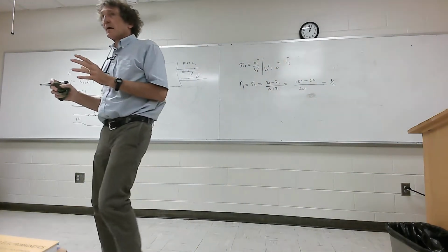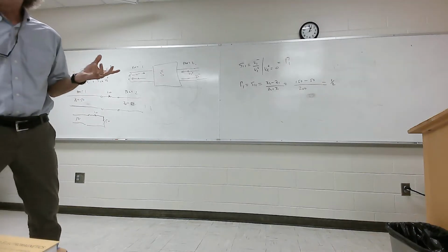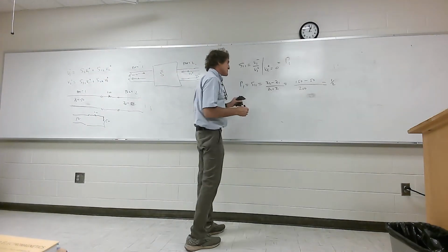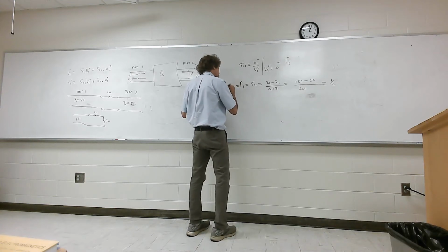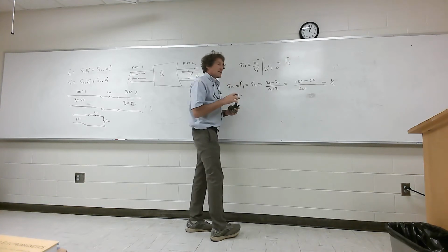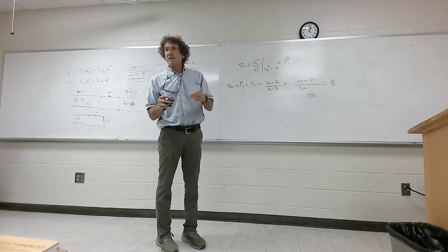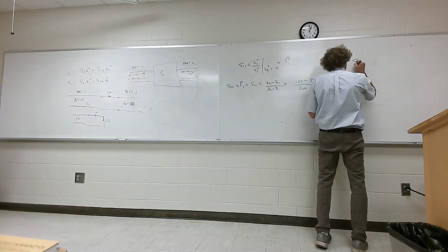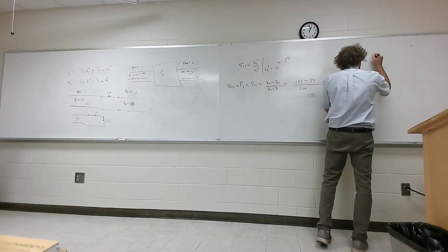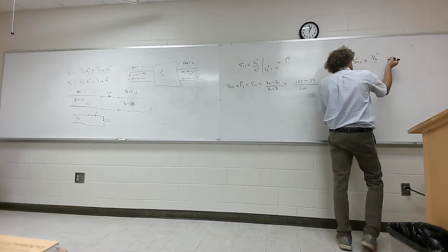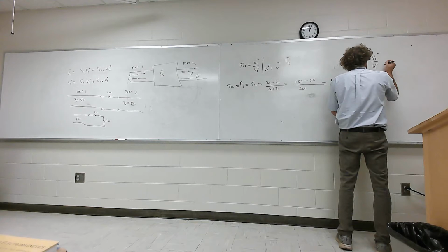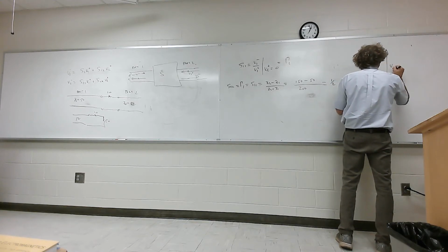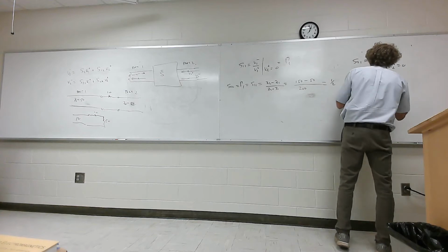Everybody? All right, now, the transmission coefficient you can get a couple ways. We'll get this will be S11, it will be S22. Now we need to get S21, and it's important you appreciate this. When I'm talking about S21, that's equal to V2 minus over V1 plus, assuming V2 plus is 0.